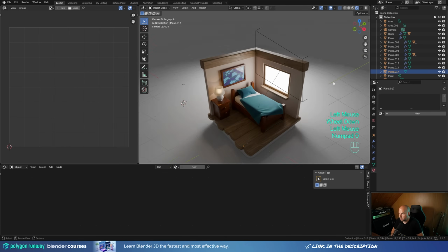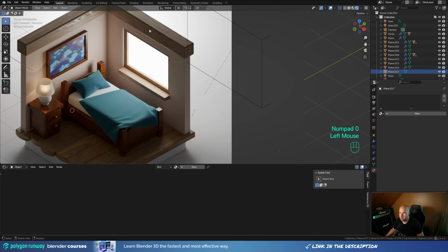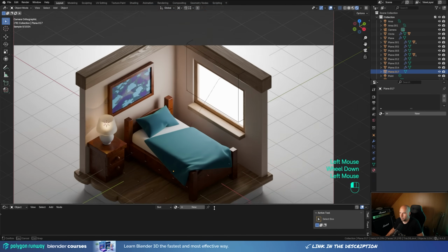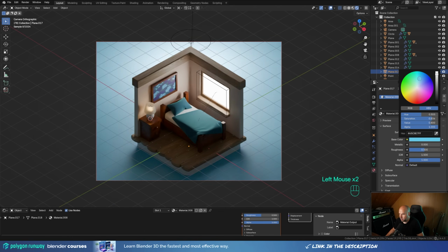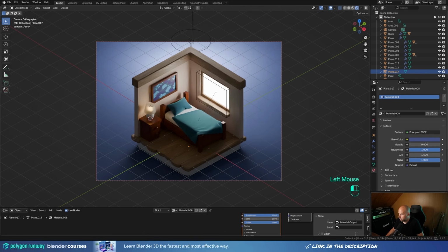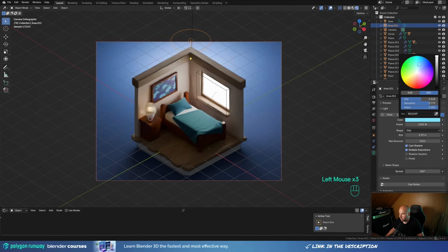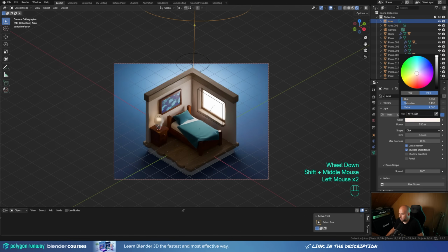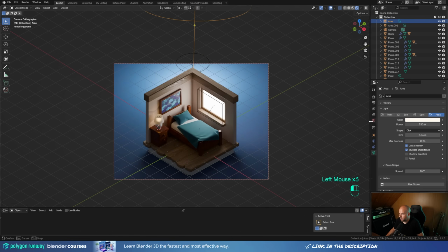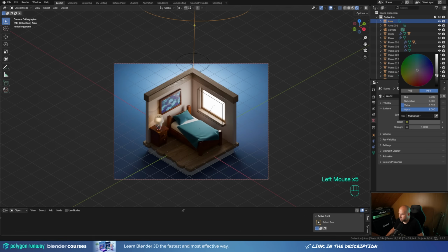Let's select the background. Let's look from the camera, and I can collapse the UV editor now. And let's add some material there as well. Maybe something blue, a little bit darker with a little bit of roughness. And now here we can select this background light and add some color to it like this. And here finally we can tweak this color as well. And in the world settings we can add some color to blend it all together.